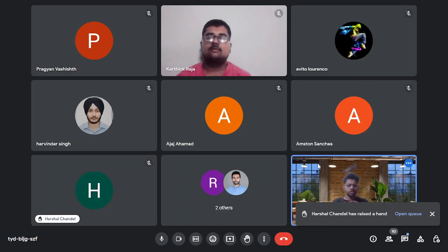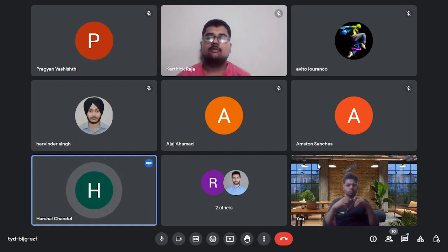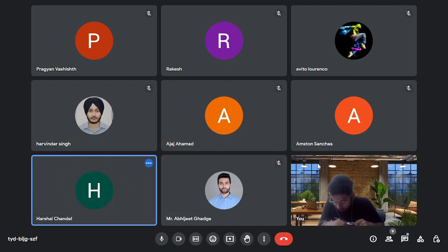Yeah, Harshal. See, magnetic particle testing is something like this: if you are passing the waves through it, and there's a crack, that wave will leak, and then the particles that you have sprinkled on the surface will accumulate there. So the magnetic field you are passing through the material will attract those metal particles, so you get to know that there's a crack over there.